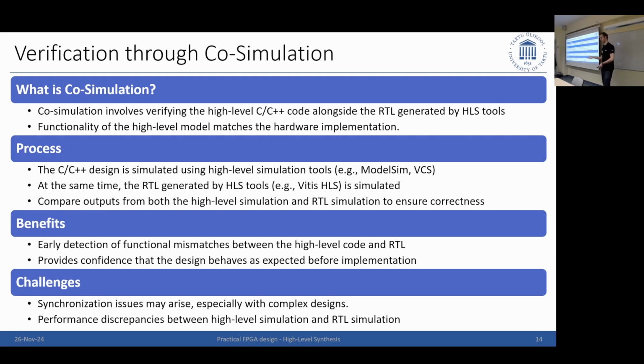And the more I test in my test bench, the more I can be sure that it actually works the same way. If I have just an adder, A plus B, 1 plus 2, and I write a test bench to do that in simulation in C++, and it does it on both sides, then I can be quite sure. But if I have an entire algorithm with a lot of parameters fed in, then I need a more complex test bench to make sure that these things work. Benefits: of course, I have very early detection of functional mismatches, because I do not want to go further into my process with the same problem.